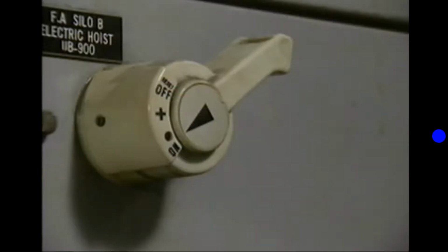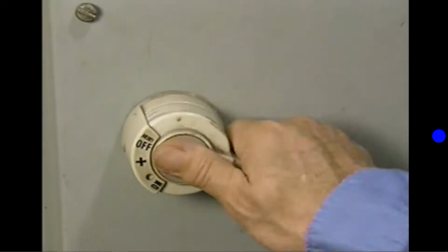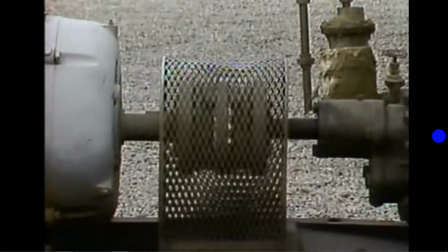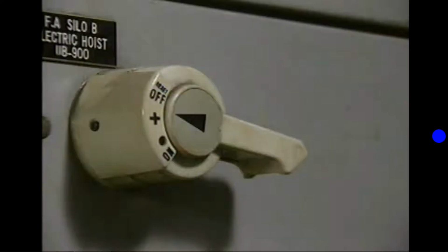For example, when the breaker handle is in the on position, contacts inside the breaker are in the closed position, completing a path for current to flow from the feeder to the motor. And when the handle is moved to the off position, the contacts inside the breaker open to disconnect the motor from its power supply. Under abnormal operating conditions, the breaker's contacts open automatically to protect the motor branch from excessive current.